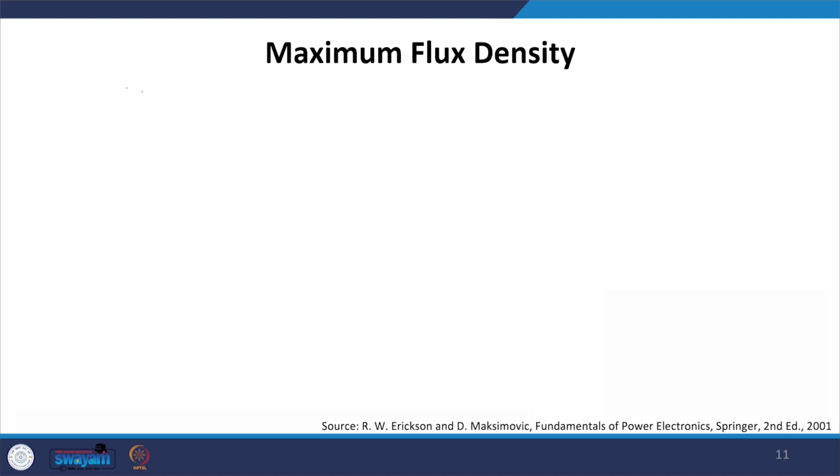Now we already know from Faraday's law of electromagnetic induction that our flux linkage is equal to the integration of V1 of t dt, where V1 of t is an arbitrary periodic input given to the primary winding.